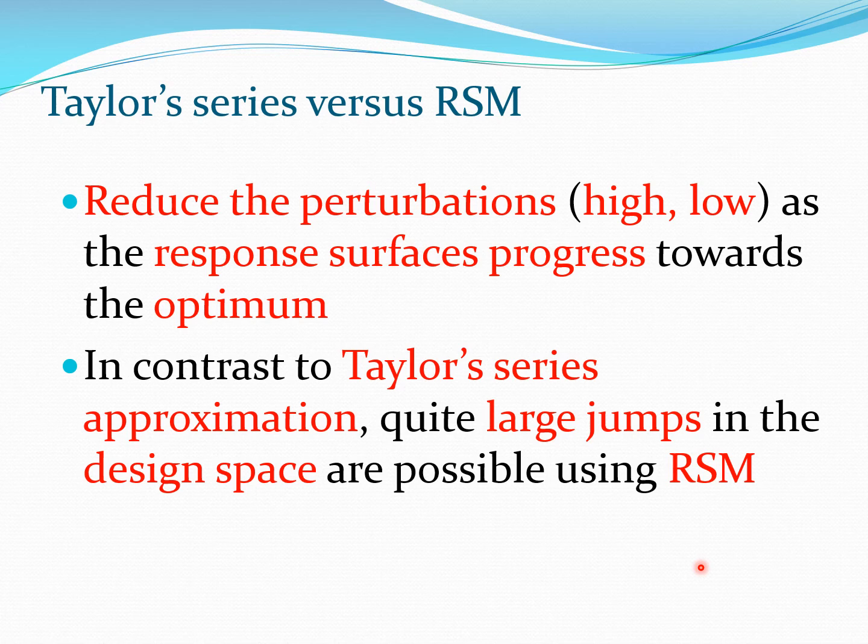So I think some researchers such as Van der Plaats have commented that this method was actually being used a long time ago, but it was in the garb of these kind of rough Taylor series methods, and then later it became more solidified because of the statistical background which came from response surface methods, and then that helped us develop this DOE type of framework which takes 15% or 25% perturbations from the center point rather than the 1% or less type of perturbations which are taken typically in the Taylor series.